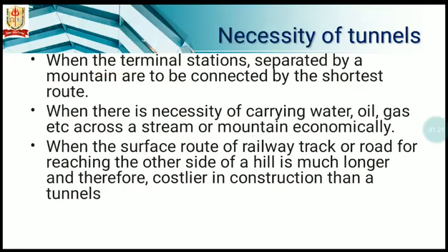Necessity of tunnels. When the terminal stations separated by a mountain are to be connected by the shortest route, when there is a necessity of carrying water, oil, gas, etc. across a stream or mountain economically, or when the surface route of a railway track or road for reaching the other side of a hill is much longer and therefore costlier in construction than a tunnel.